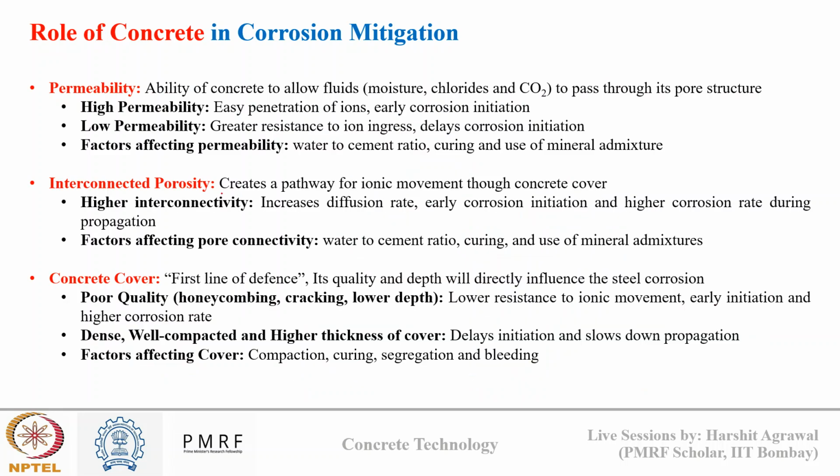How? If you see, permeability is the ability of concrete to allow fluids to pass through the pore structure. So if I have a very high permeability, ions can easily pass through concrete, and corrosion can happen early.